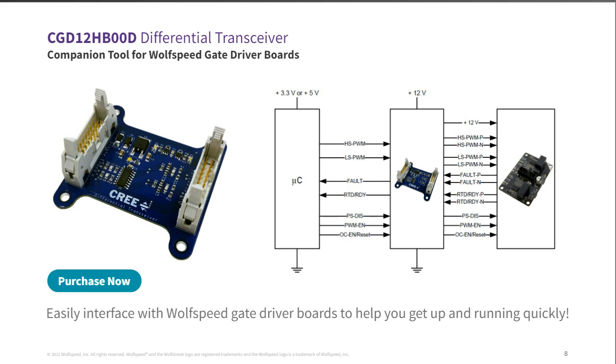The critical signals like the PWM and the fault feedback, the RTD and temperature sensor feedback signals, are differential. We found that this is a pretty simple design choice to make to really increase your noise immunity. But we also realized that most people might not be set up to provide differential signaling that easily.